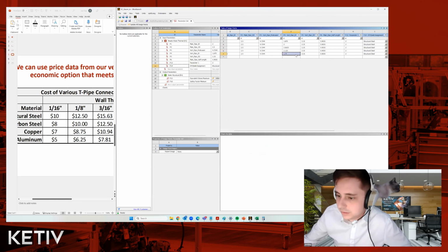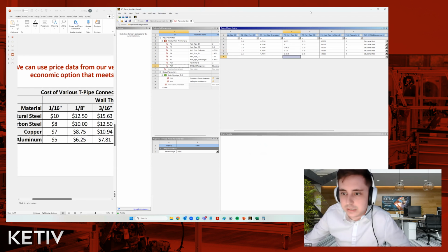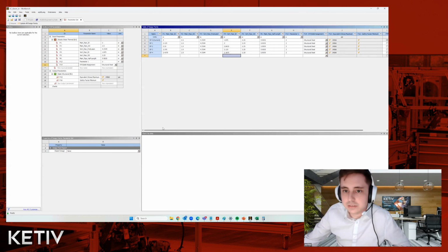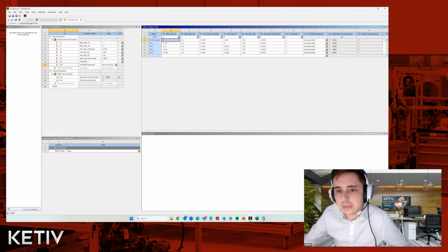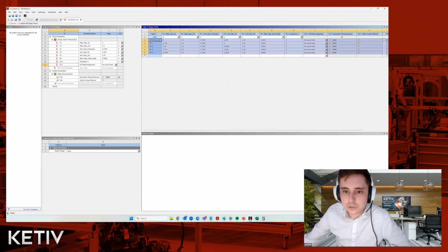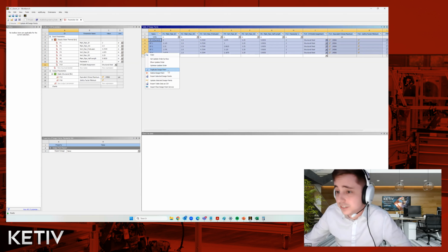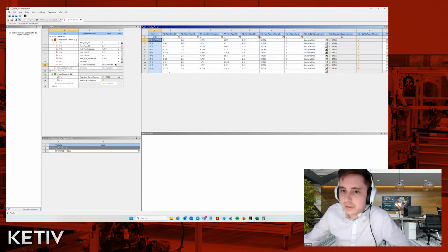Okay. So now we have all of our different pipe thicknesses assigned, and now the pipe goes from its thickest to its thinnest state. And that was a lot of work, right, for this one material. But luckily, if we just Control Shift select all these different rows, we can actually duplicate these design points. So we don't have to do that again, right? Because we don't want to do that again. And we can simply adjust the materials.